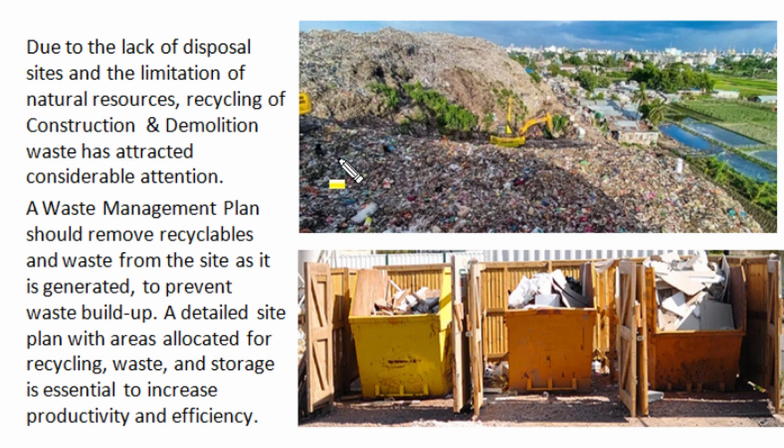And a good waste management plan should remove recyclable and other waste from site after segregation as it is generated, to prevent build-up of waste material on the construction site. And for that, a detailed site plan with area allocated for recycling waste and storage is essential, and that increases productivity and efficiency of construction and demolition waste management.